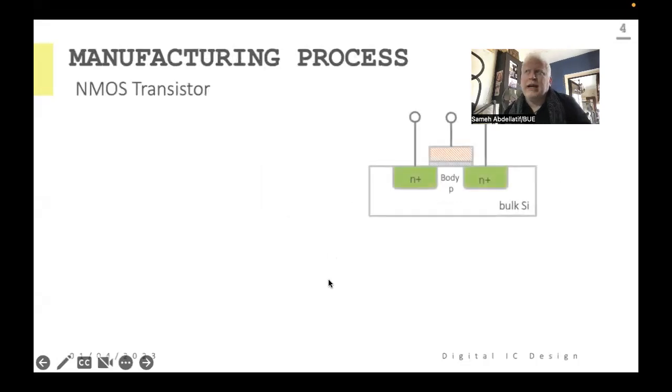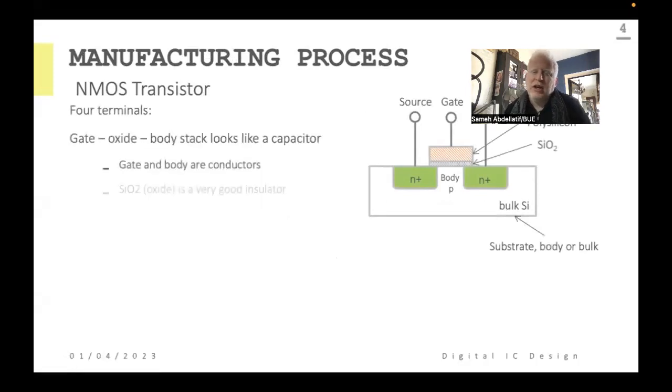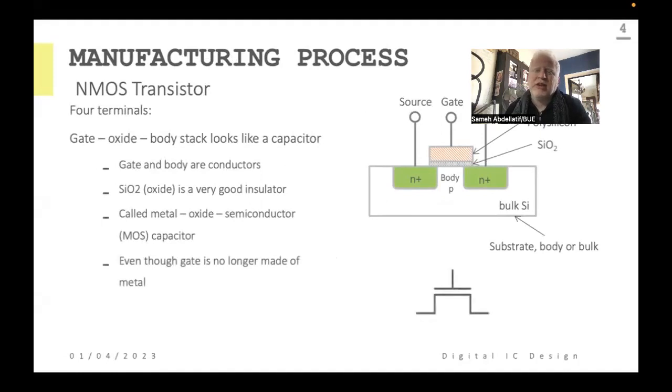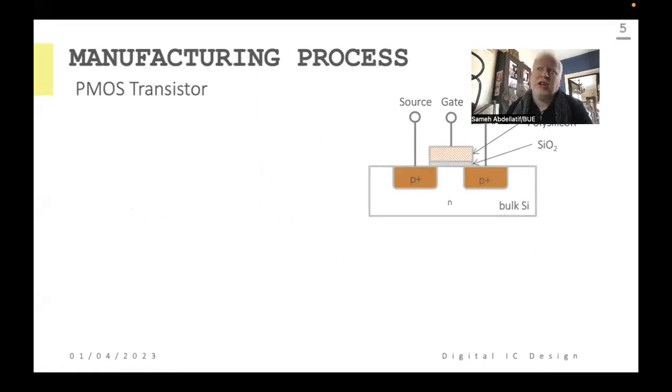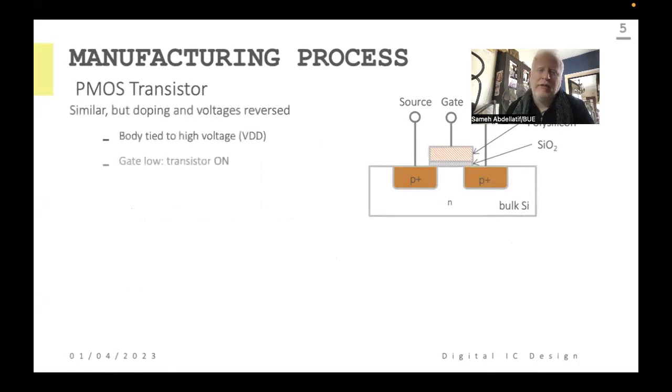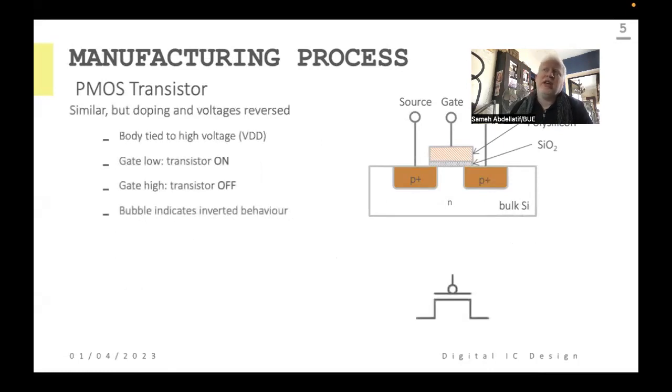Okay, so this technology is seen in terms of CMOS technology, either in the N-channel MOSFET, as you can see in this case, where we have two N-doped regions in a P substrate, or in a P-channel MOSFET, where we have two P-doped regions in an N substrate, or what we can call the source and drain doping wells.